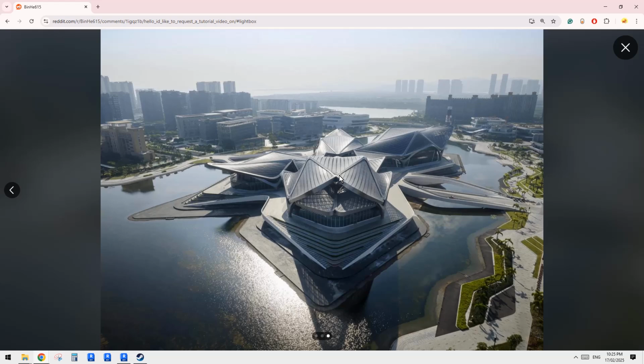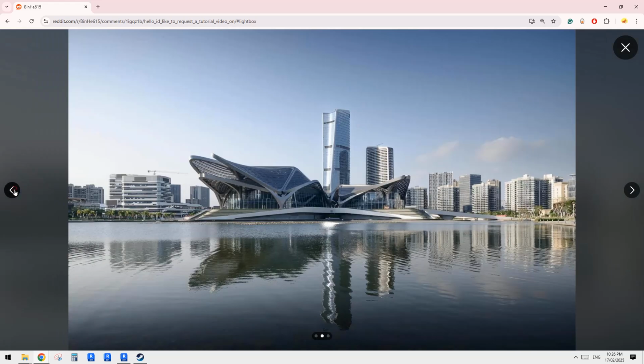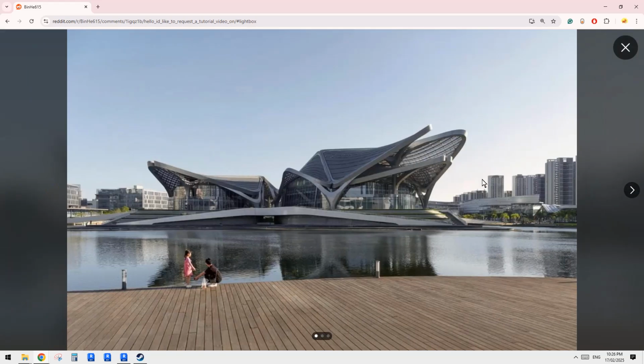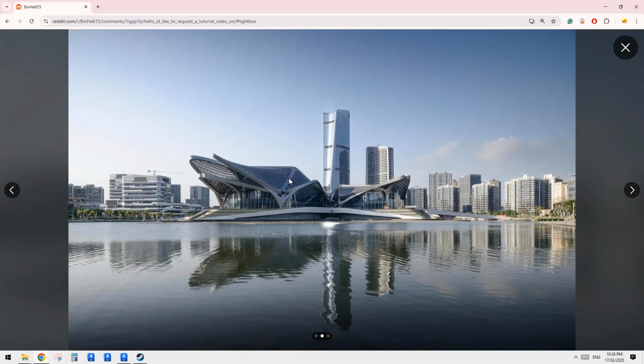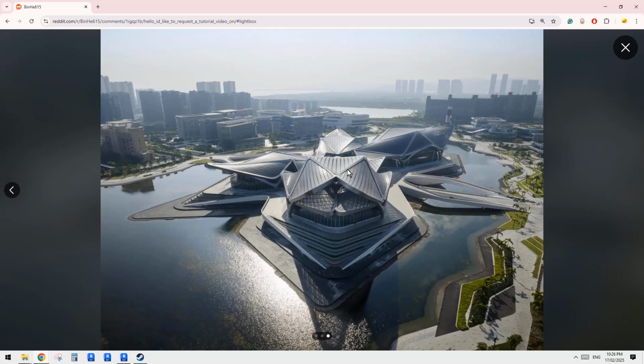So just use a basic roof to create something like this. There's no better angle for that roof, but imagine you're trying to create this shape. Not the one in the middle, not the curved panel pattern, which can be a pattern-based family, but see the shape of this.